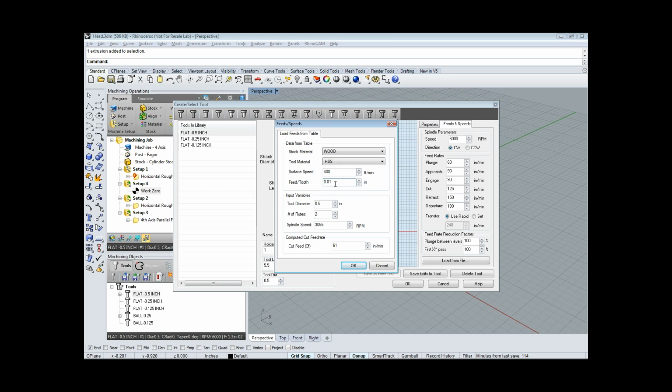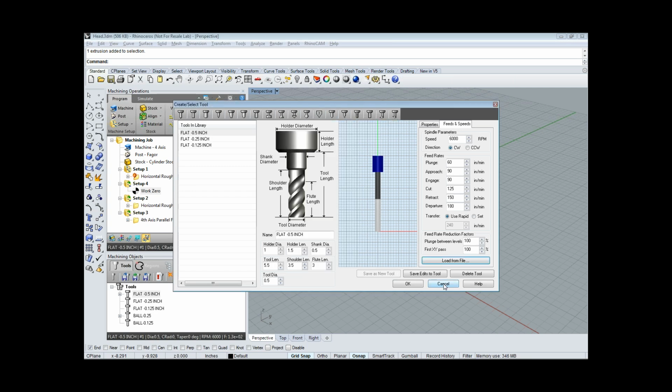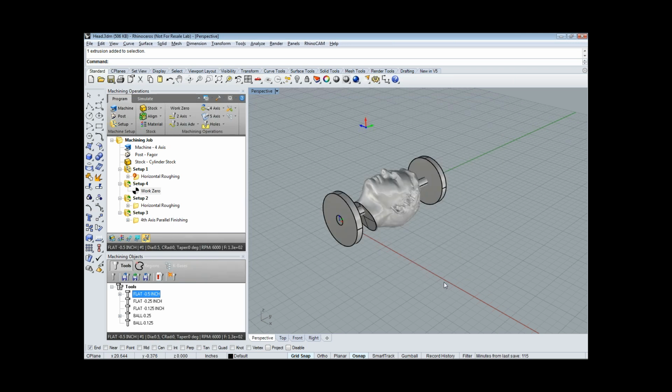All right. There are many types of operations. How does one choose the best one? This might be a little bit of a loaded question. That's right. Based on the geometry, it could be whether a 3-axis or 4-axis, or if it's a part that requires just prismatic, it needs 2-axis or 2.5-axis programming. There are a lot of help files and tutorials available in RhinoCAM you can refer to, and you can learn what kind of operations can be used for a specific application.